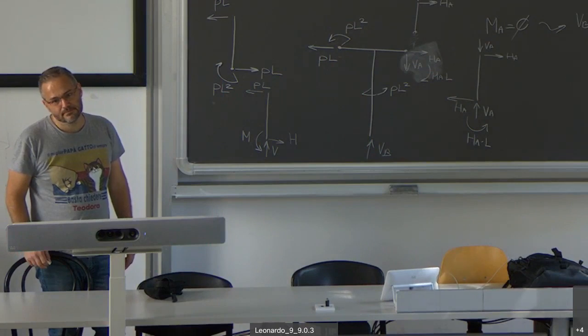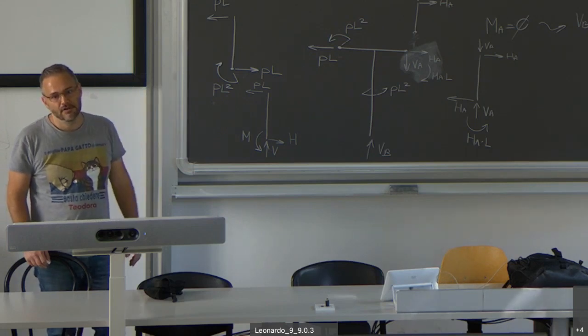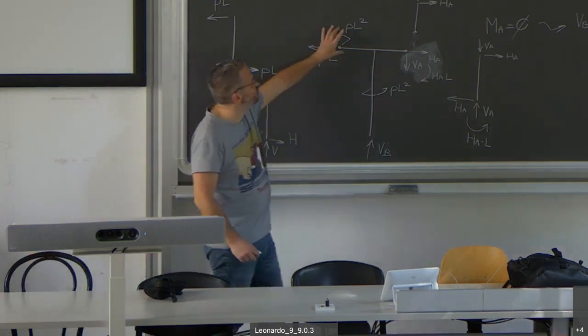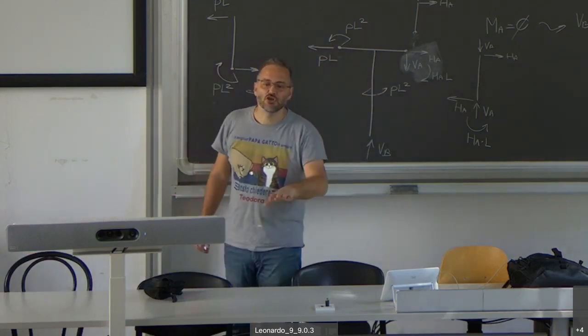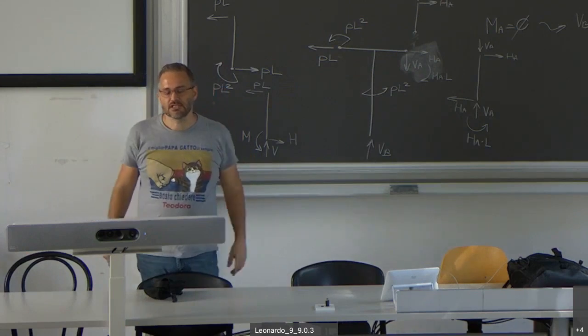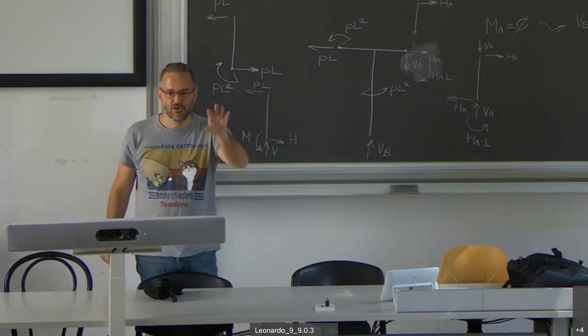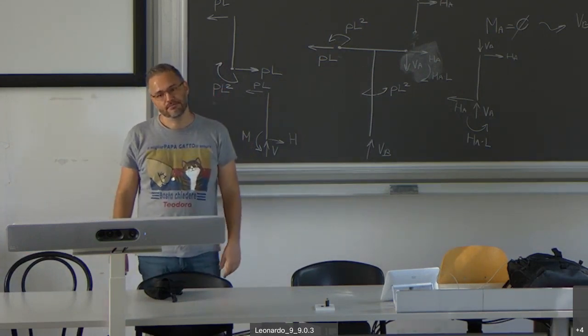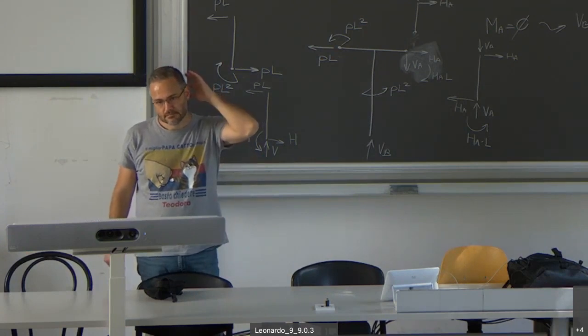They're independent of lever arm and distance. Their contribution is a number. When you have a concentrated bending moment applied, its contribution does not depend on the distance from the reference point. It's always the number with its direction. The reference point is at the top right.